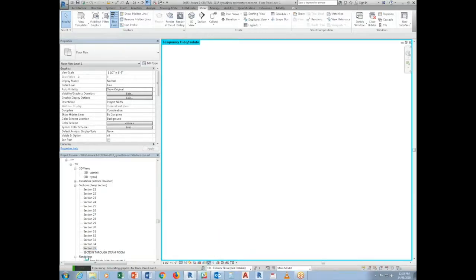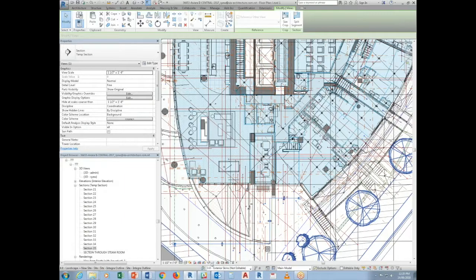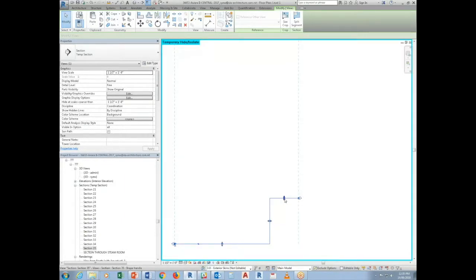So what happens is that every time you create a dependent, it creates another tag on top of that. Just something to keep in mind. Because right now, is this the one? Yeah, that's the one. And what you're going to do is isolate it. Just move it back to normal. Okay? Then you can just do crop. So if you do encounter where certain things just would not move, then do this, right? Just figure out whether there's a section that has a jog, because the jog will prevent a crop from moving anywhere. So that's basically one of the anomalies of dealing with Revit views.